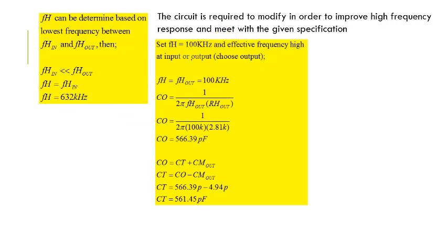In this case we can choose either input or output. For this case we choose the output. So we set our high cutoff frequency at 100 kilohertz.